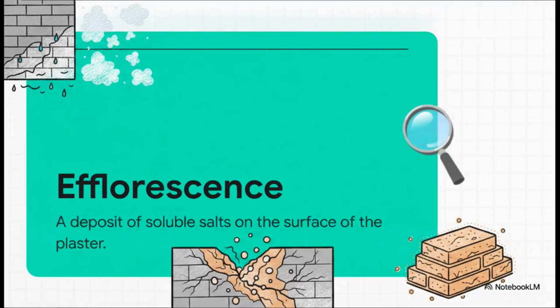background. Now let's look at two major chemical nightmares: efflorescence and sulfate attack. If you plaster over a wall that's suffering from rising dampness, or if you use bricks with a high sulfate content, the moisture acts as a catalyst. Efflorescence leaves these stubborn, white, powdery salt deposits all over your finish. Meanwhile, a sulfate attack is even worse. It causes a volumetric expansion that physically disintegrates your mortar and plaster from the inside out. No one wants to deal with that.